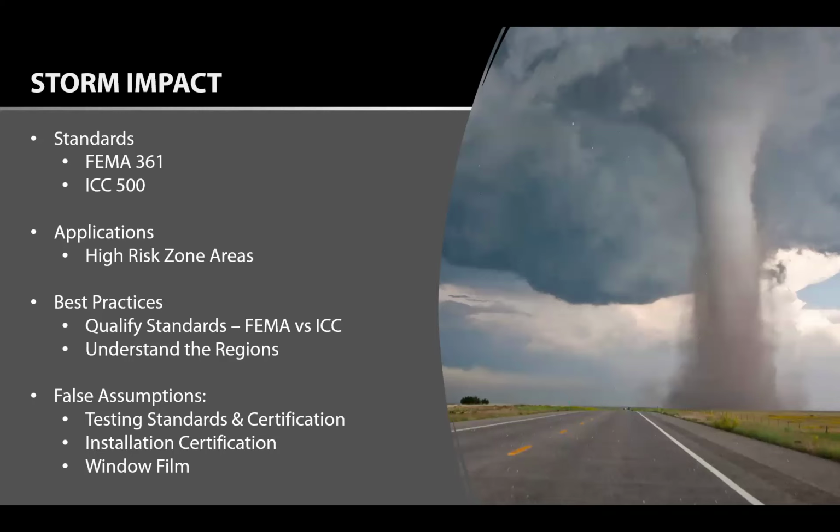Now, I would like to talk briefly about window film and some of the unfortunate marketing that has gone along with window film, because I will say this about film. Film has its place in the world for decorative, privacy, bird-friendly, animal-friendly applications, but not when it comes to security. Many window film manufacturers out there have marketed the material to be ballistic rated, blast rated, and storm impact rated. Unfortunately, it is not. So please, please do not fall for that marketing scam.